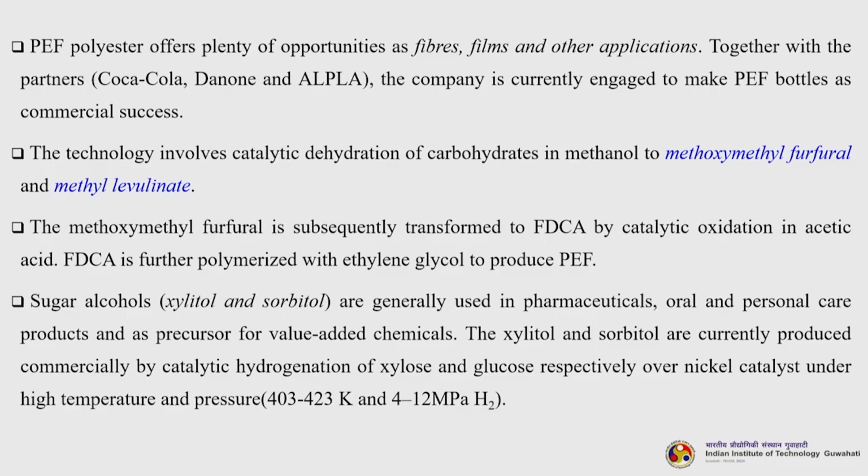Together with the partners, that is Coca-Cola, Danone and Alpla, the company is currently engaged to make PEF bottles a commercial success. The technology involves catalytic dehydration of carbohydrates in methanol to methoxymethylfurfural and methyl levulinate. The methoxymethylfurfural is subsequently transformed to FDCA by catalytic oxidation in acetic acid. FDCA is further polymerized with ethylene glycol to produce PEF.